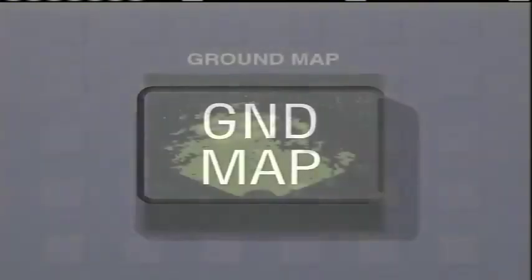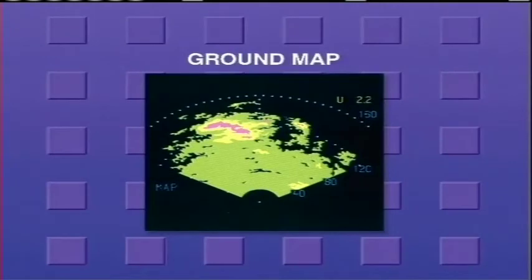To use the radar in ground mapping mode, first press the Ground Map button. Then adjust the antenna tilt control downward until the terrain appears. Ground map colors are green for weak returns, yellow for moderate returns, and magenta for intense returns. The map symbol will also be displayed in the lower left corner of the PPI.